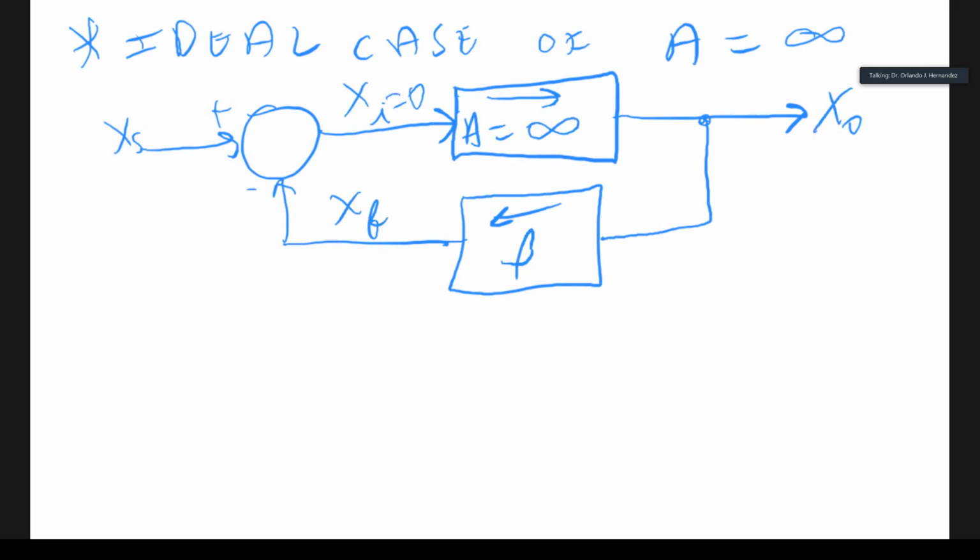paradigm in op amps. The A gain of op amps is so high that, and remember these are linear systems, for the op amp to behave linearly, you have to have both inputs be very, very close. Otherwise you get distortion and no linear operation. Well, this is sort of related to this. We're saying the error, or the difference, which is the same thing, the difference between the inputs of an op amp is zero because the gain of the op amp is so high. Okay?